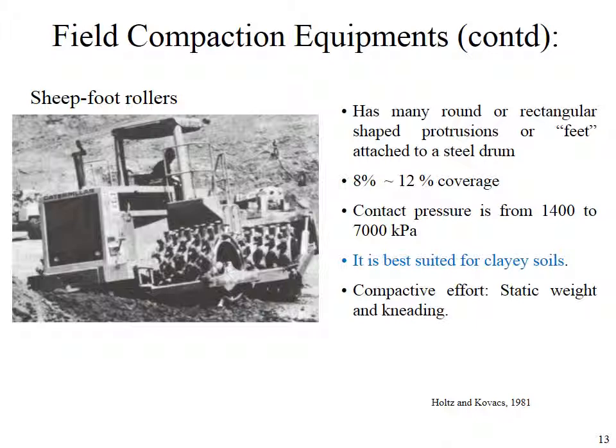Sheepsfoot rollers have many round or rectangular shaped protrusions or feet attached to a steel drum. 8% to 12% coverage. Contact pressure is from 1400 to 7000 kilopascals. It is best suited for clay soils, and compactive effort is static weight and kneading.